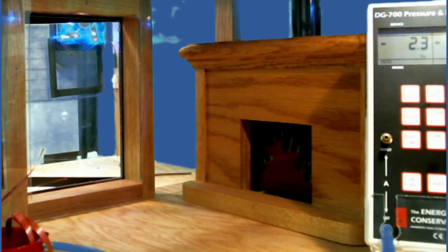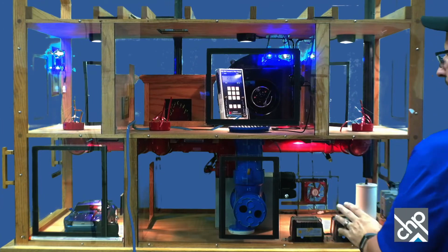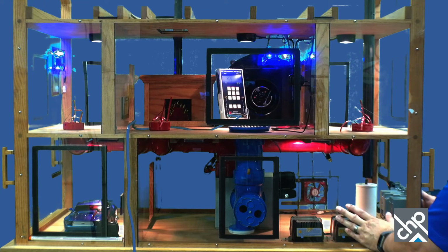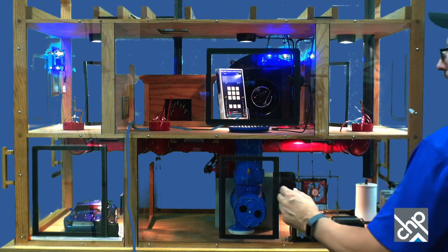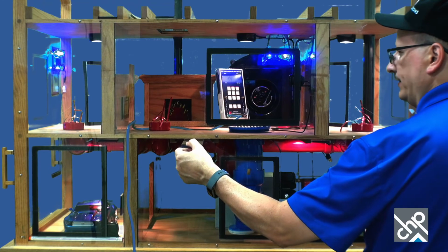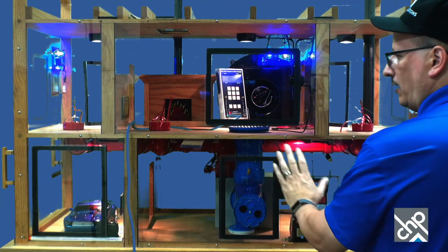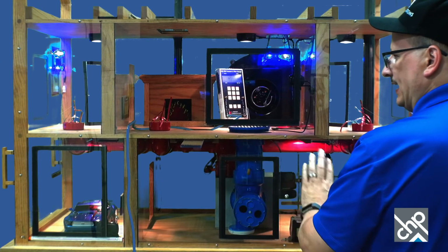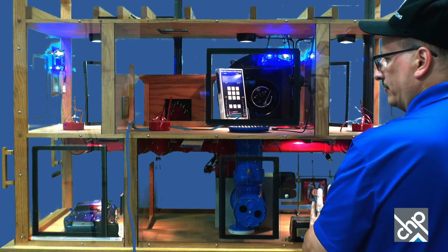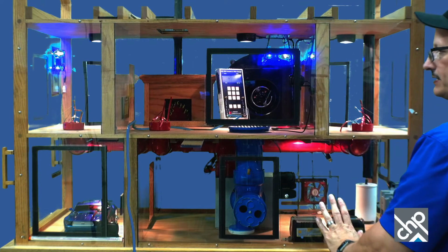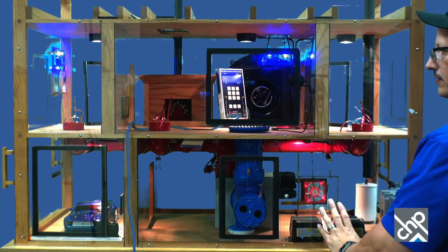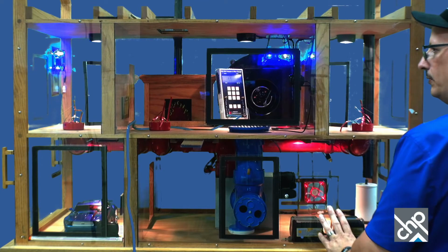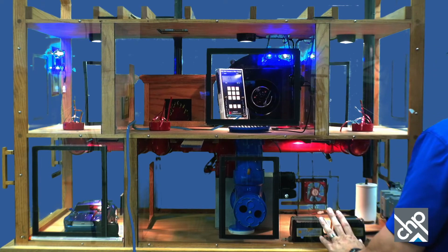Now I'm going to go back out here where you can see me. I'm going to go down into the basement and turn on the dryer. Actually, I'd have all the interior doors open. In this case, we'll just call this a basement or laundry room, but let's say it's conditioned space, and I've got the dryer down here. I'm going to turn it on, and we'll see if it affects the pressure upstairs. So we're at about 1.7. I'm going to turn it off, and then go back to the inside view.